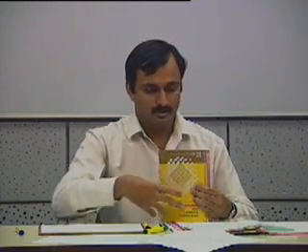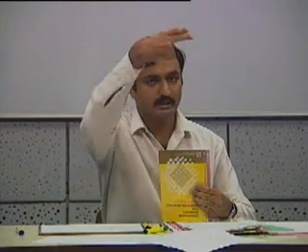But if the projecting plane is at an angle, then I will get the vanishing points. If my projecting plane is like this and my block is vertical but at an angle, the vertical lines will still appear parallel, but the horizontal lines will appear at an angle in the projection. So in the vertical direction there will be no vanishing point, but in the horizontal direction you will get a vanishing point. Is that clear?